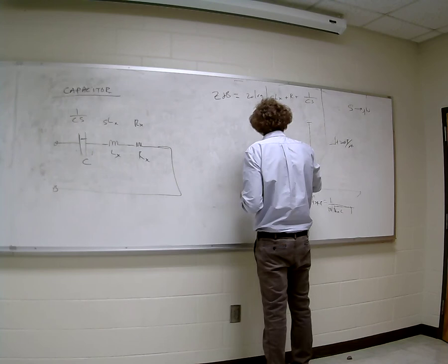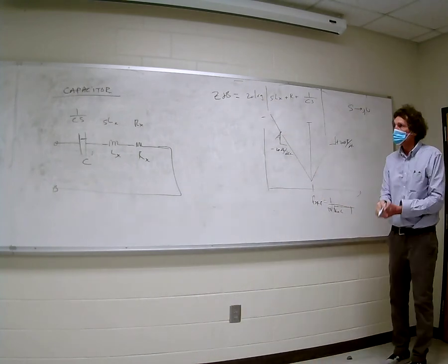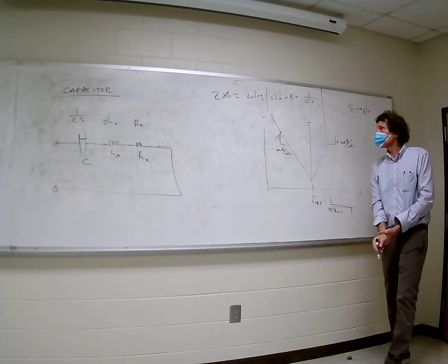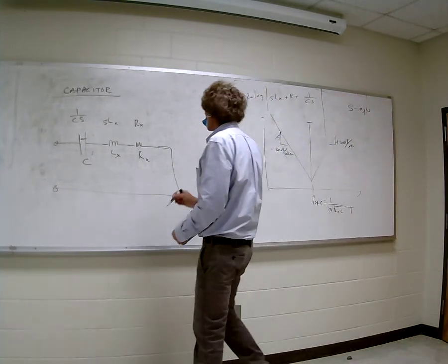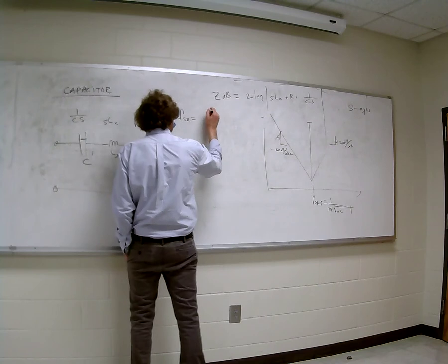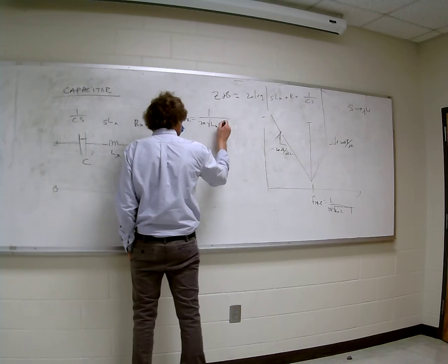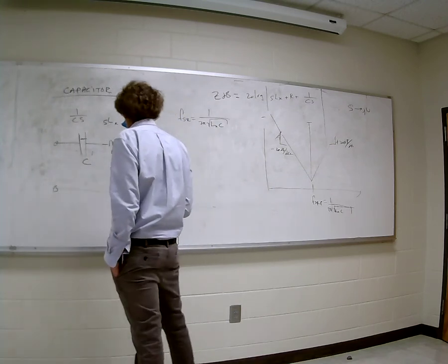This is going to be minus 20 dB per decade here. Are you with me? And the self-resonance, I didn't put that down. Well, I did there. Same in all, self-resonance.